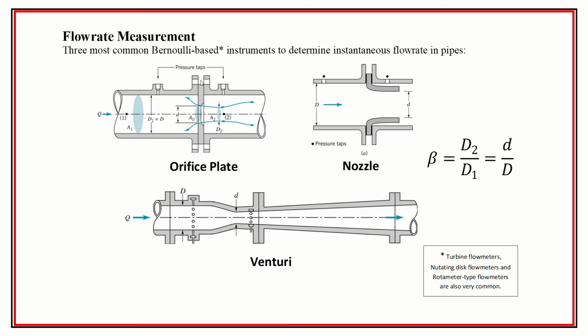So we have this blockage in the system. It's got a little hole in this plate that's blocking it. And because of the pressure drop across this plate, we are able, from some calibrated curves, because these orifices are kind of standardized, we can find out based on that pressure drop what the flow is with a correction factor.